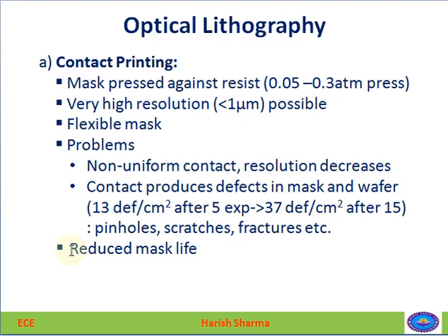The mask here we are using is flexible. It's not hard like glass. It's flexible like plastic. The problems are, we are just placing the mask against the surface. So there may be some portion that is not touching the surface. There may be a gap between the mask and the substrate region.